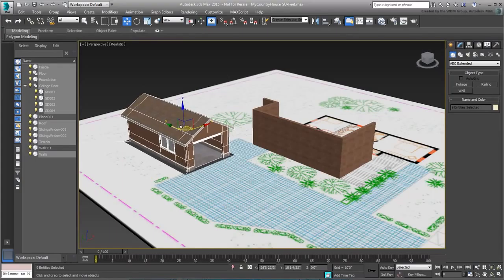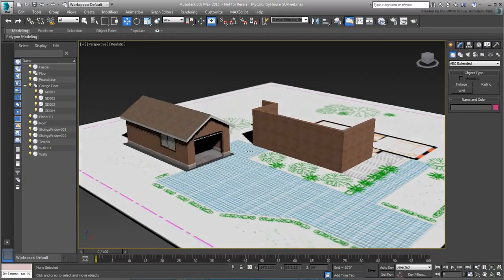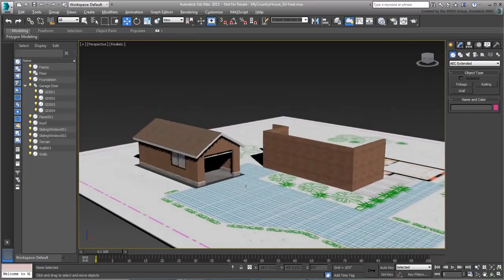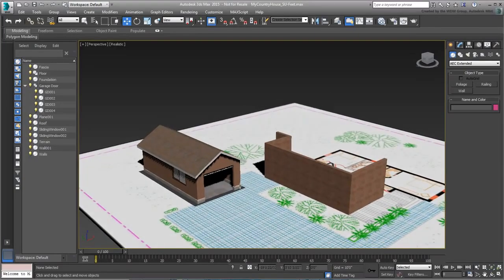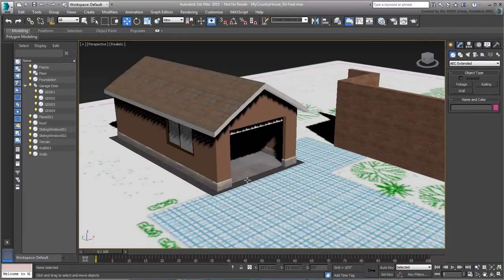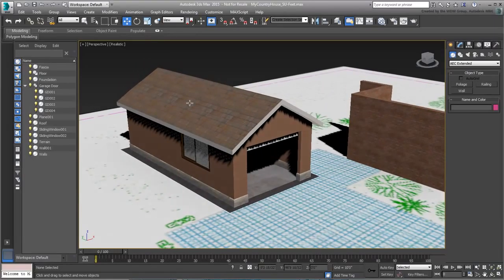At first glance, everything looks good. Certainly size-wise, there are no apparent problems here. The Merge tool took care of any needed scaling so that the width, length, and height of the structure work well in the scene. In fact, select any object that makes the garage and choose the Scale tool. Note the transform type ends and that the scale of any object that makes the garage is still set to 100%. This is significant, and this is how it should be.